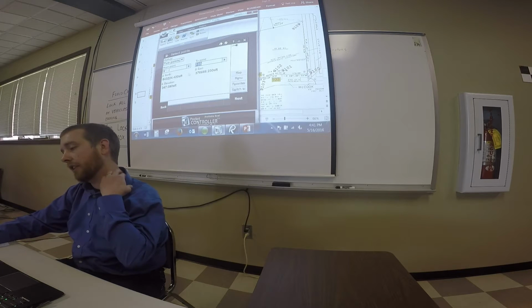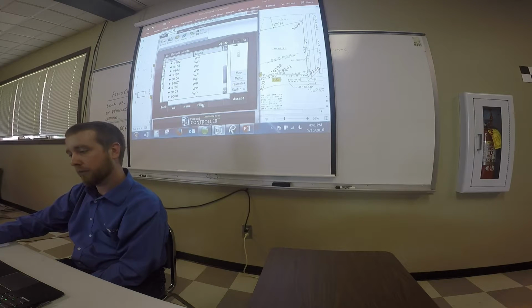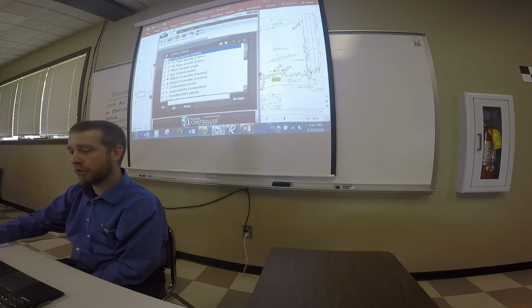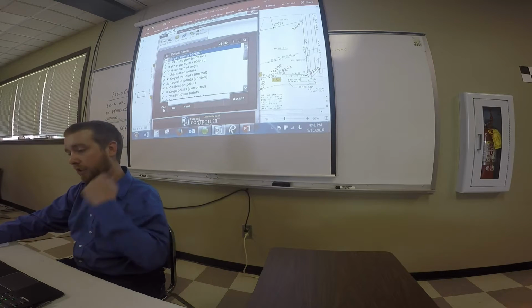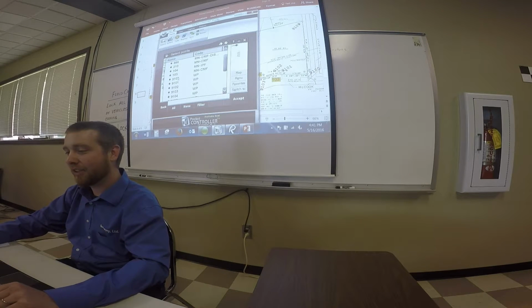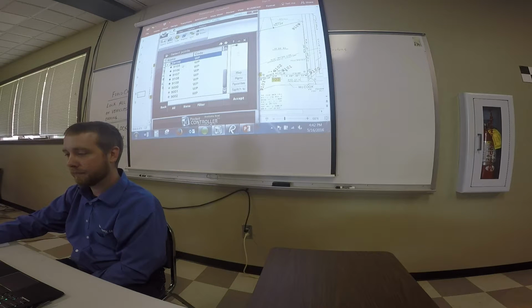Okay. Click next. Now it brings up a list of your points. And you can filter these points by hitting the filter. You can turn off your topo points. You can turn off your stake points, but you want to keep on your keyed in points. It'll bring up the list of all the points you've punched in, which in this example is all of them because I punched all these points in. So you'll have to select each one you want to move. 9101. And just keep tapping on all of them to select them all. There we go, that's all of them.